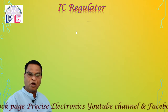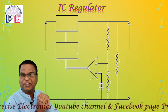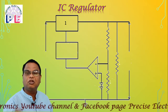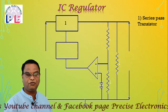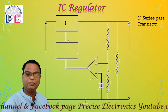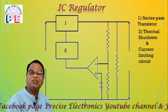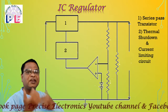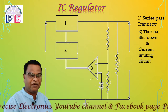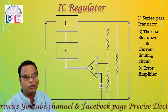Friends, now the block diagram of the 3-pin IC regulator is going to be displayed on your screen. The first block is known as the series pass transistor. The second block is known as the current limiting and thermal shutdown circuit. The third block is the error amplifier, that is also known as a comparator.